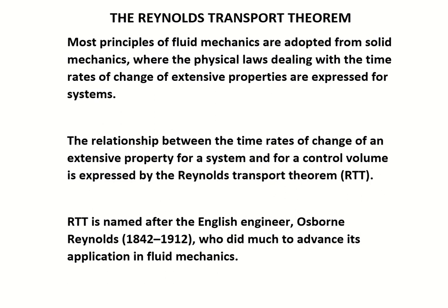Most of the physical laws, like Newton's second law of motion or other laws, are developed for fixed mass, or we can say are developed for systems. But in fluid mechanics, in many situations, we use the control volume.